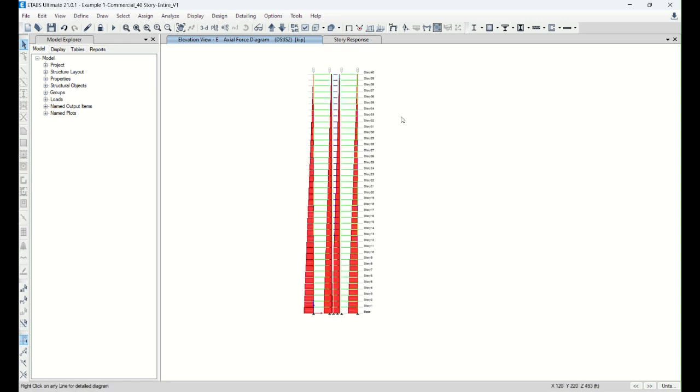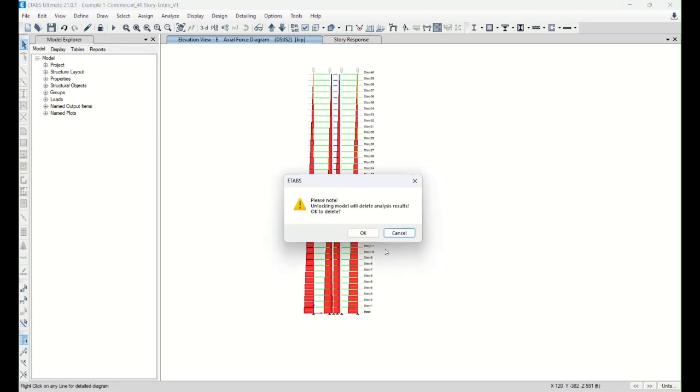But now, since we still lack lateral stiffness in the short direction, the Y direction, we try to add the outrigger truss. Then we'll see how this outrigger truss diagonal member is going to interfere or pick up some gravity forces and dump it to the wall. So that's something we need to be aware of, and I'm going to show you.